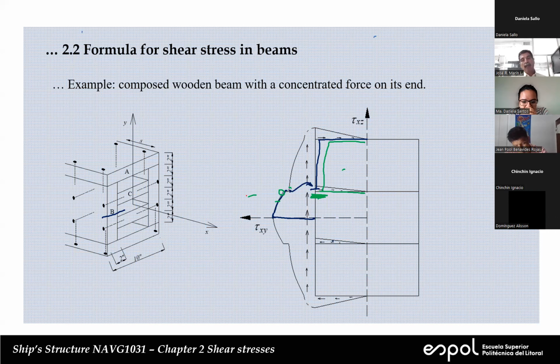Okay? And then in each one of the flanges, we know that the Y is constant. So the only variation is in area. And the area varies linearly with the length of the sector. So that's a linear variation.